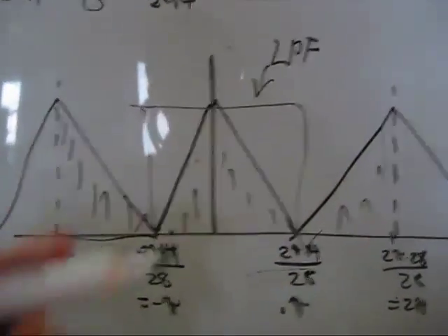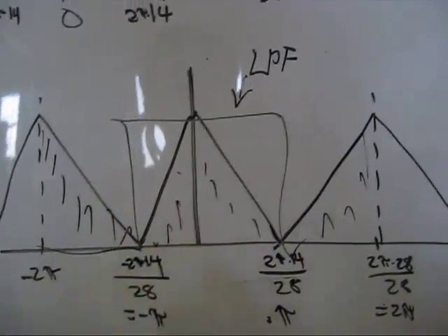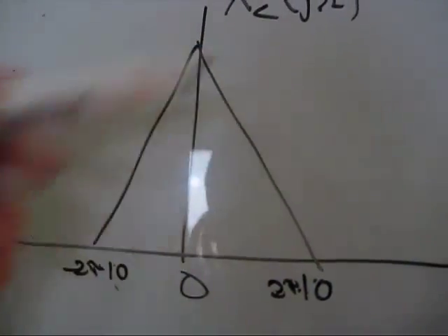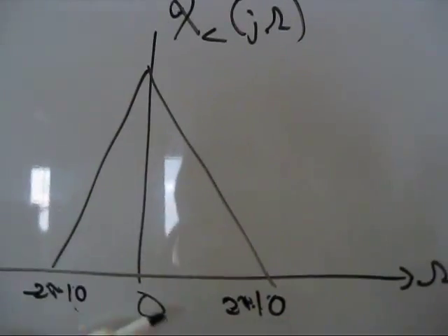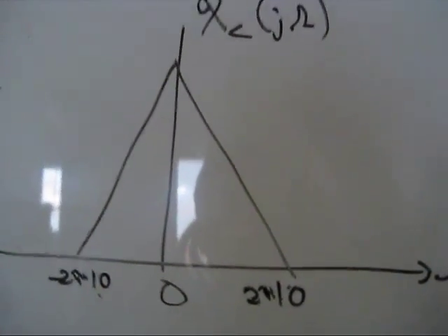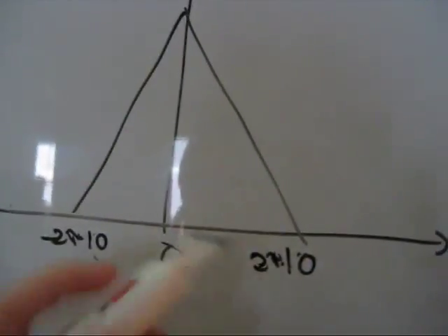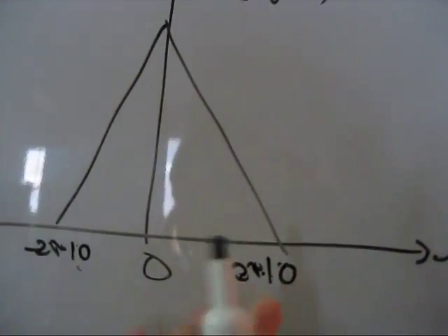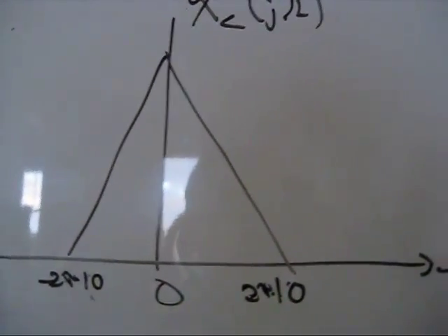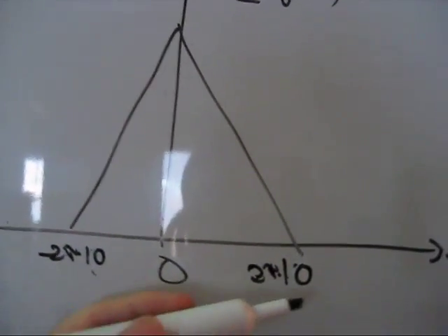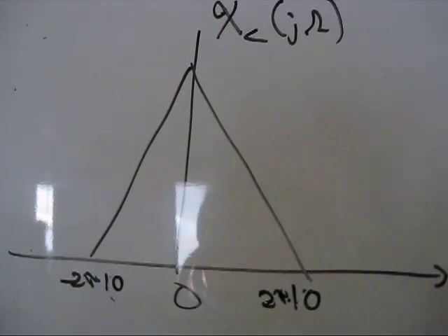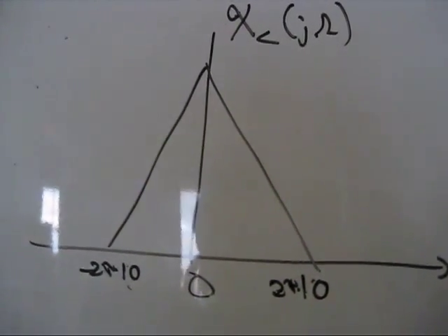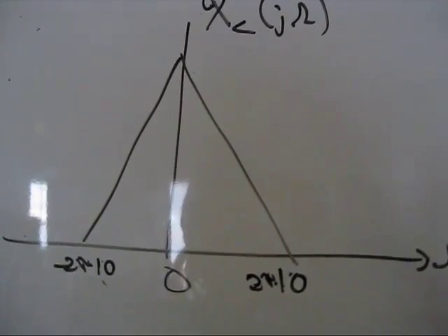So, how does this become a problem? Well, let's take a look at that too, shall we? Let's take the same idea that we had before, the spectrum centered around 0, going to plus 10 hertz and minus 10 hertz. Just for clarification, I did change it from 14 to 10, for illustrative purposes. Normally, you'd have to sample this at 20 hertz in order for the replicas to not touch. But let's say we sample it such that they do touch. So obviously we're going to be sampling it at less than 20. So let's say 15. All right, let's take a look.